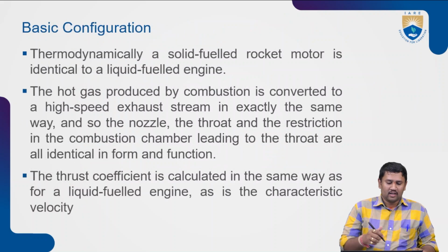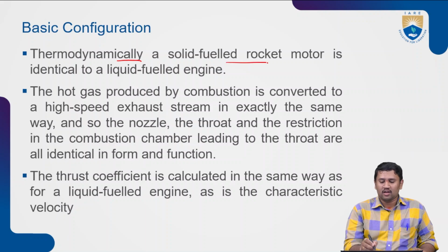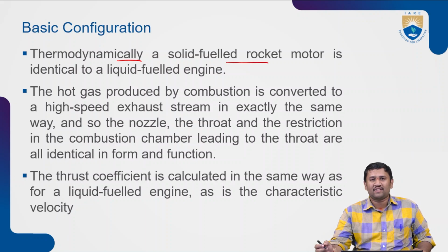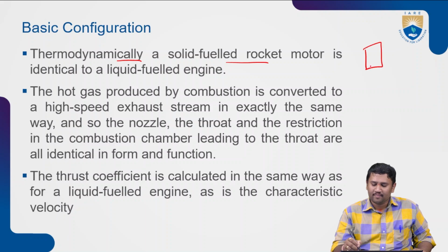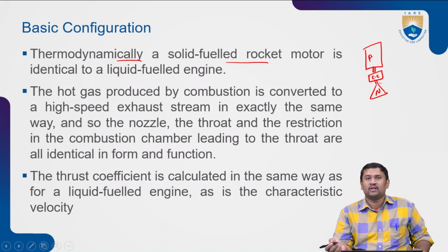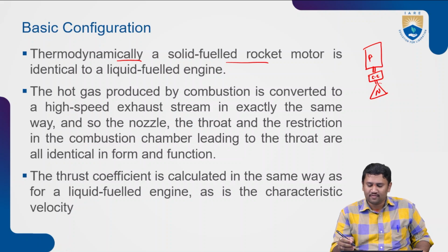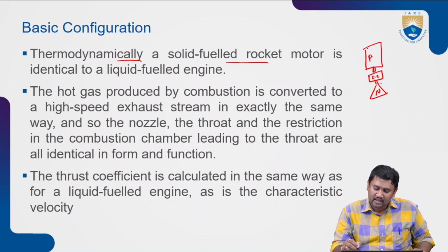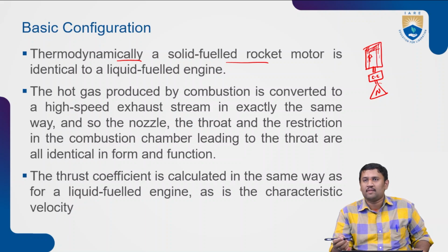Now, thermodynamically speaking, a solid fueled rocket motor is identical to your liquid fueled engine. Basically, a propellant, a combustion chamber, a nozzle, right? Now, in case of the liquid as well as solid. In case of solid, what happens in the propellant casing? This will be my solid propellant inside my combustion chamber.